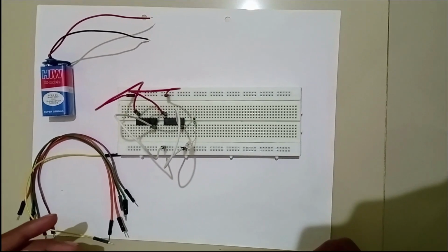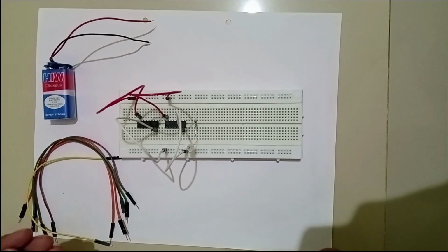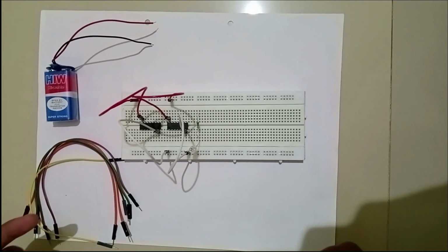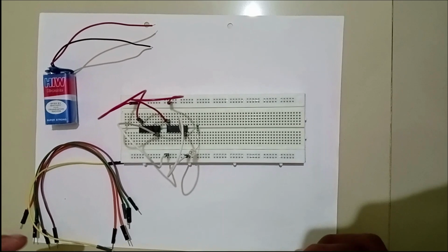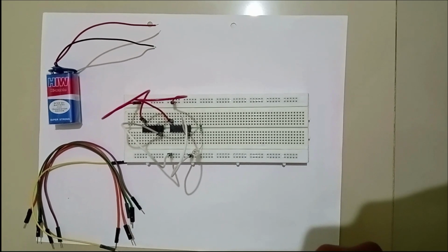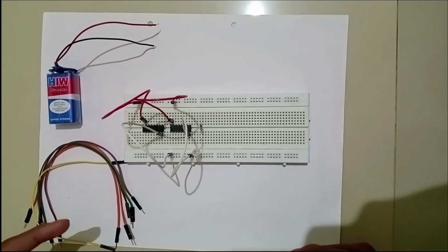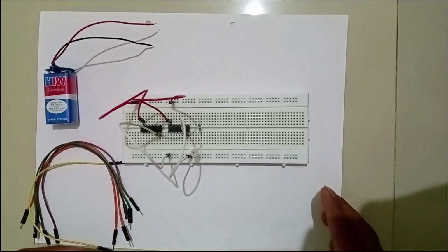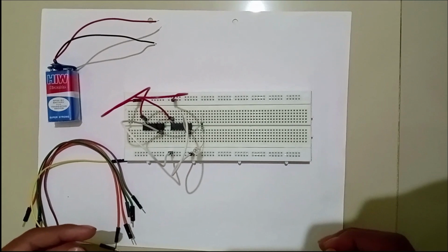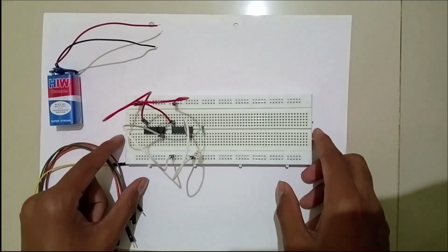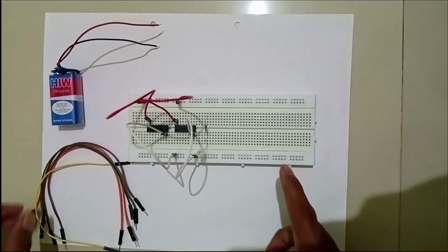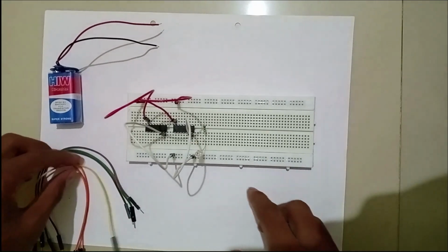We already know the BCD code is valid between 0 to 9. When we get the input between 0 to 9, the output will be 0. If we get a decimal number greater than 9, the output is 1. Now we verify the conditions in the truth table.